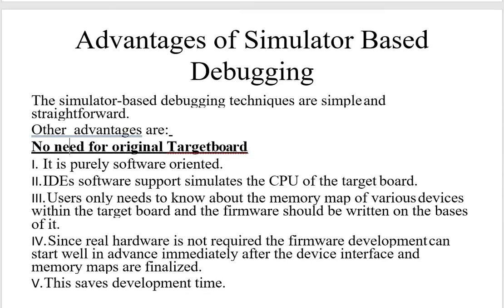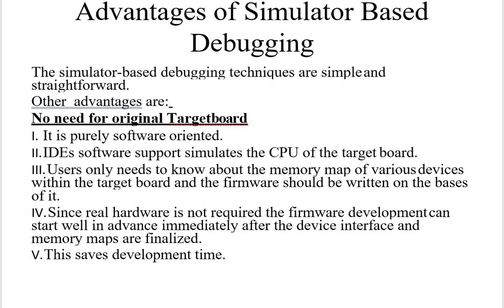The advantages of simulator-based debugging are: it doesn't require the original target code. It is purely software oriented. IDE support simulates the CPU of the target board. Users only need to know about the memory map of various devices within the target board, and the firmware should be written on the basis of it.